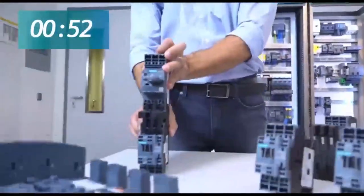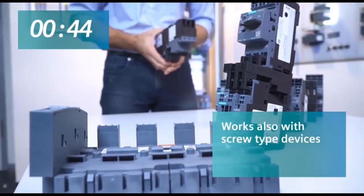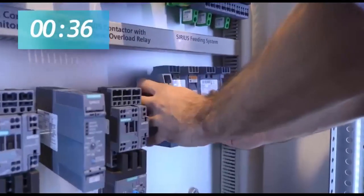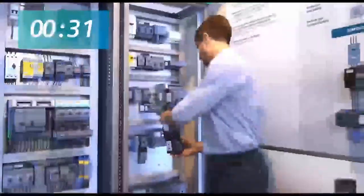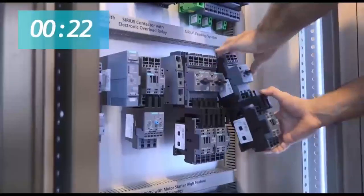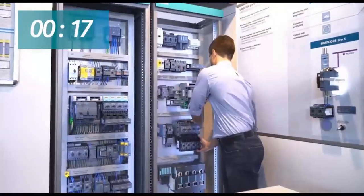Using the proper link module between the contactor and the MSP, I'm now assembling the 4 starters. You just need to align and push. Align and push. And please note that the infeed system will also work with screw type devices. You just need to use the proper links. I'm now adding the base in the control panel by just snapping it down on the DIN rail. I'm adding now the 4 starters like so.